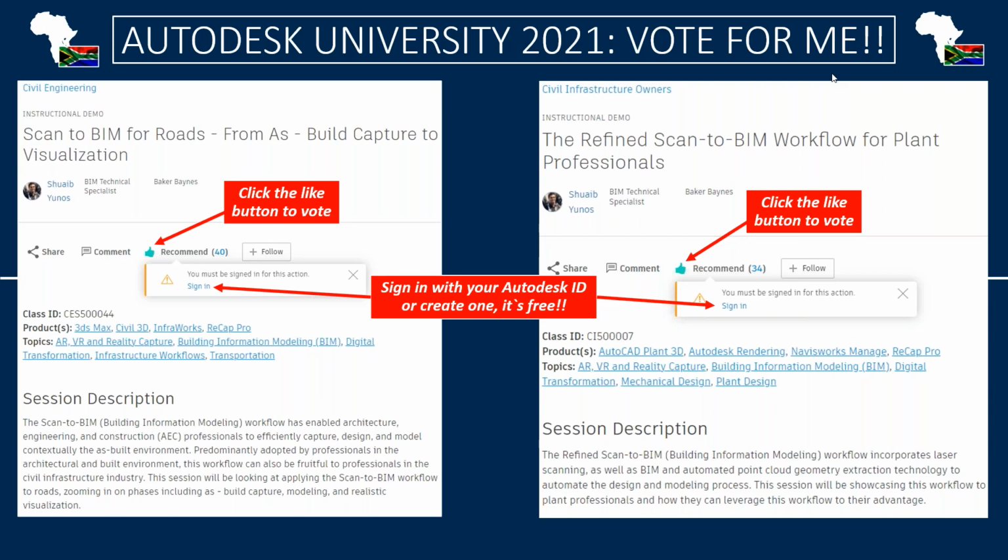Okay, there's another one here. Can you explain what a decoration is? I am confused. Okay, so in InfraWorks, you've got different aspects. People always get confused about this, especially when they come for training the first time in class. There's a difference between a component and a decoration. A component is normally assigned to a road, where you can add certain features that come through to Civil 3D. When it is a decoration, it does not come through.